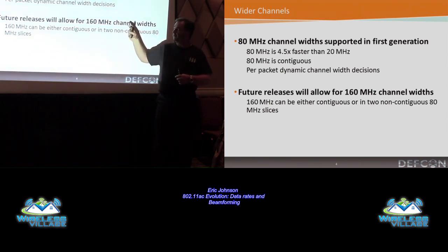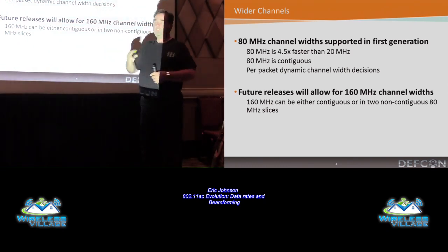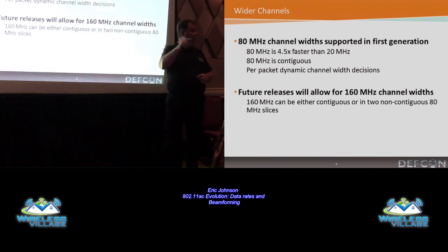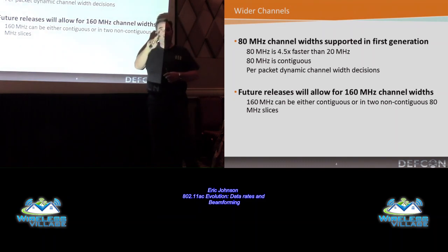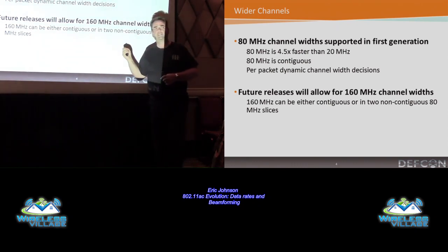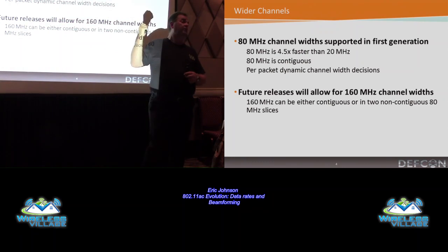This is something I'm not going to touch on today, but it's actually a really neat feature that gives you the backwards compatibility. It actually allows 2 radios that are sharing the same 80 megahertz channel to be split. They can transmit at the same time on 40 or 20 megahertz here and 20 megahertz there. It can be extended to 160 megahertz. On the commercial side of things, we don't see that that's necessarily going to be useful. There just isn't enough spectrum.